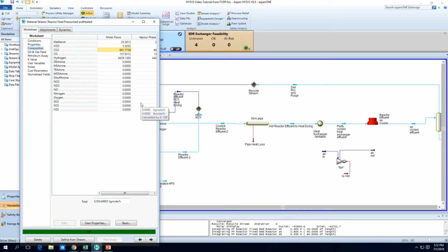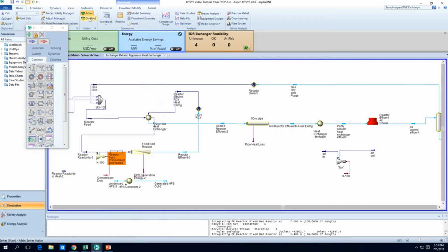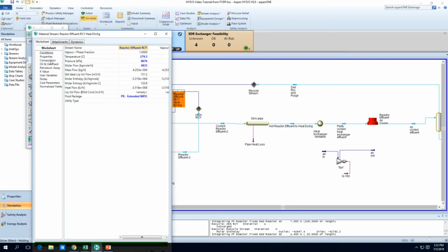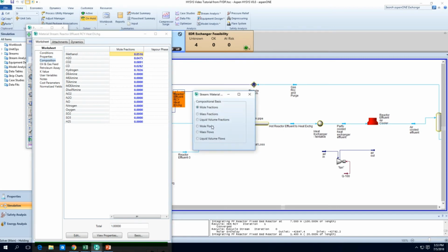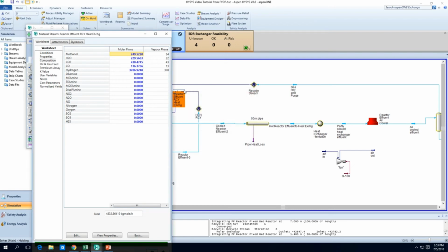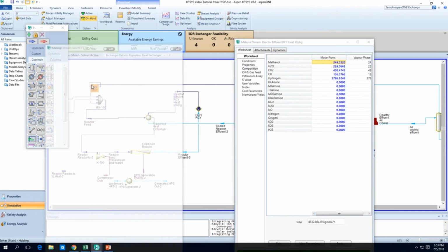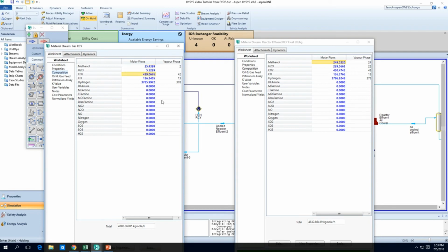674, 622. So, what do you think we can do to get it faster? You can see if the CO2 count is actually decreasing. We can skip a few iteration steps. So CO2 out is about 430. And in this gas recycle, it's also about 430. If this is decreasing, we can skip a few steps.